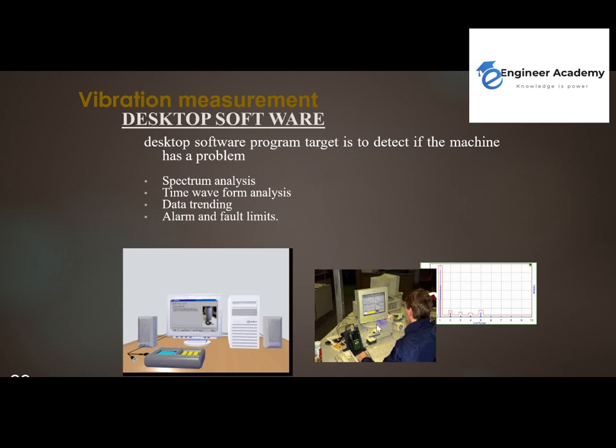This system is PC-based software, and this software gives you storage capability, analysis capability, and historical readings you can refer to when you have an issue in the machine. Then you can get the reference, do the analysis, do reporting, everything using this software. And of course, using online is a good indication. Also, you can set the online system for alarm and trip in order to protect your machine.